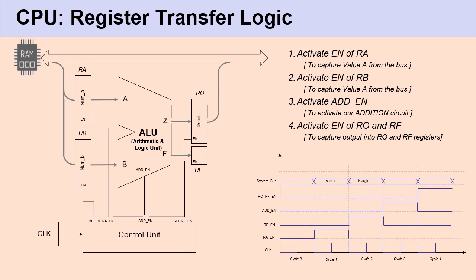So likewise, this particular operation required 4 clock pulses. So the speed at which the operation can be carried out depends on the frequency of the clock. If you have a faster clock, then operations will be carried out much faster because each step will be completed much faster. If the clock is slower, then operations will take more time. Therefore, the clock frequency of a CPU is sometimes seen as the main indicator telling how fast the CPU can work. But that is only one single indicator.